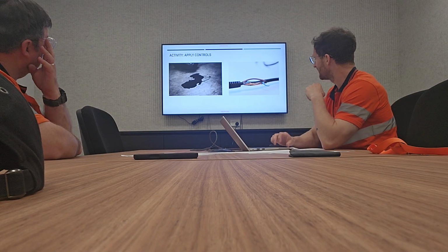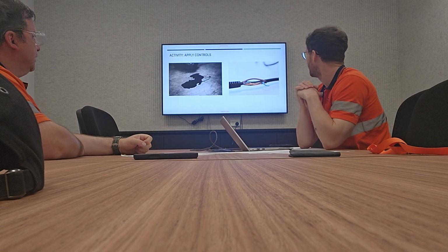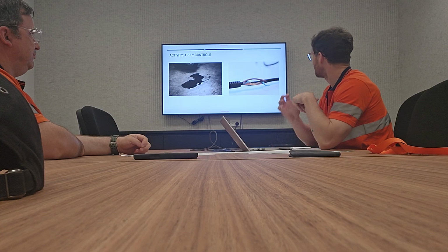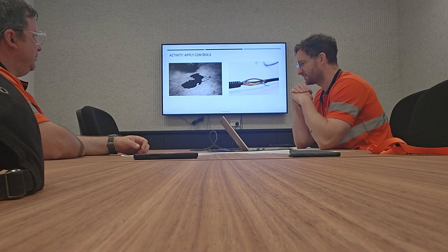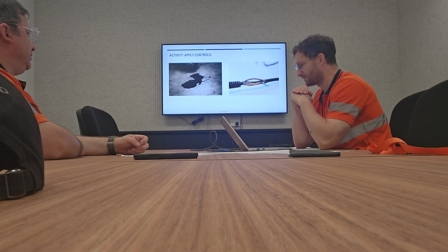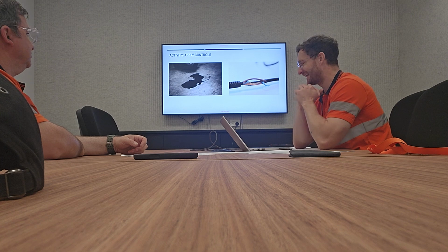Moving on to the next hazard I found. Someone had some exposed cables on a tool. Can you think of ways that you might apply controls to this situation immediately? If I saw that, I'd be pulling that device immediately out of service. And depending on what it is, if it can be repaired, have it repaired. Call an electrician in to put a new cable on it. If it can't be, then cut the cable off and throw it in the bin. Yeah, perfect. Can't add any more, I guess.